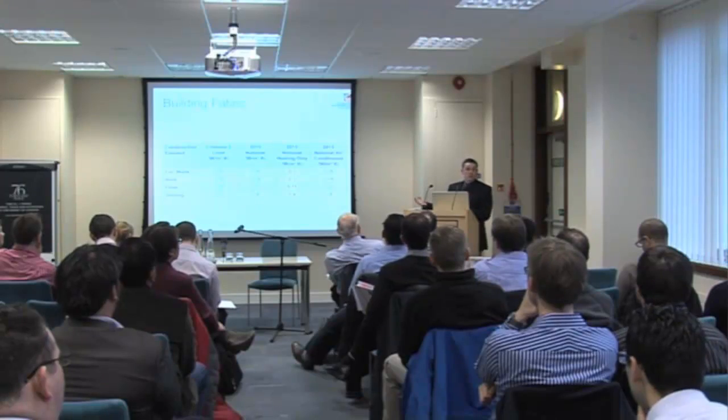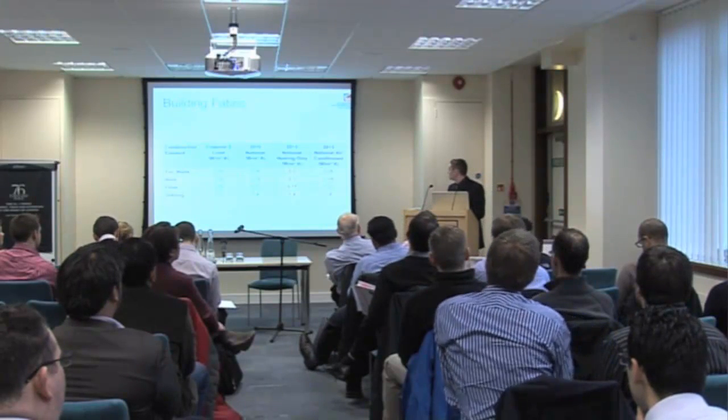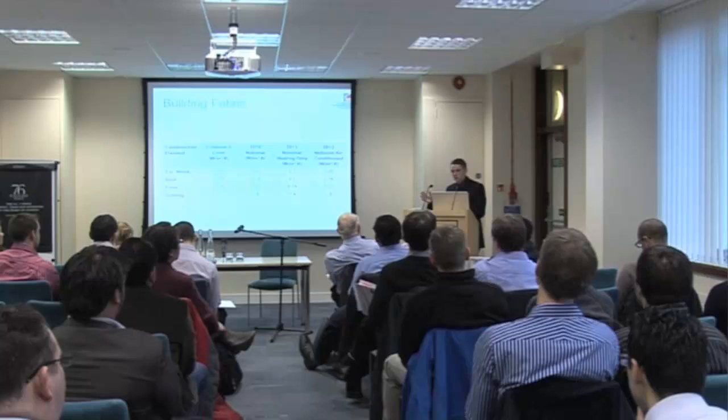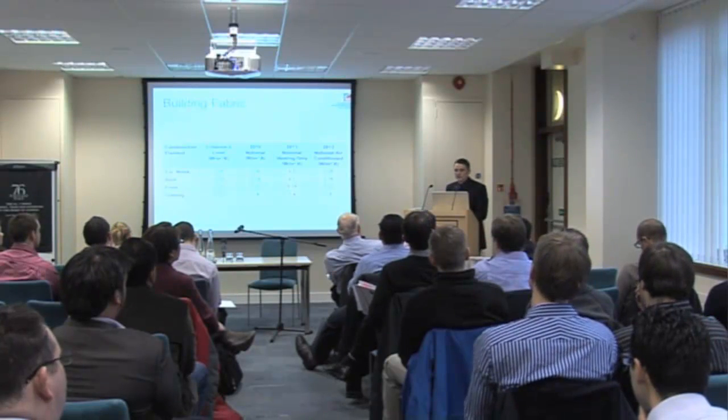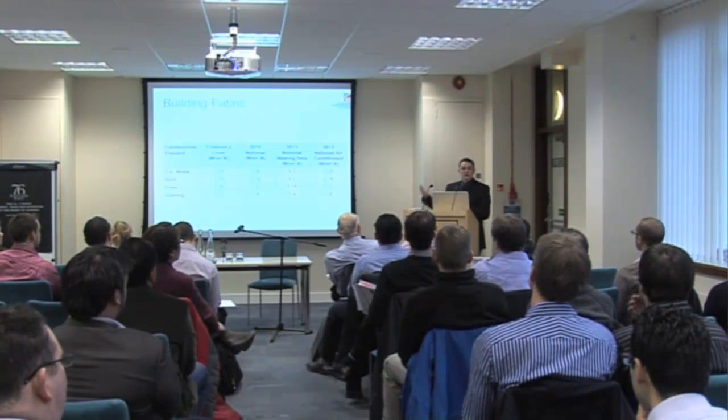I imagine if you were working in an office block in London, for example, where you've got a warmer climate, high internal gains, and overall a greater cooling load, then if you were to insulate that to a higher level, you're going to be trapping a lot of that heat in and increasing the cooling load further. So from a design point of view, I can see the advantage of having, or why you might want to have, poorer U values